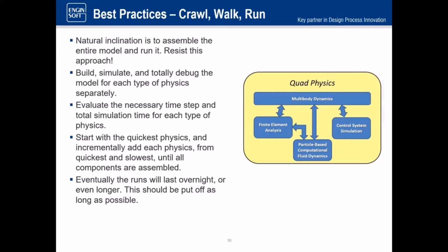And with many of these models, once you start putting in all the different aspects of the model, especially the finite element model and the Particleworks CFD model, then you may end up getting models that are going to run overnight, or even longer, maybe even several days sometimes, depending on the length of time that's being simulated. So, eventually you will get there. You want to put that off as long as possible, because then the time to tune the model, that whole process becomes very slow and tedious. So that's why you want to do all the tuning of the individual segments of the model first.